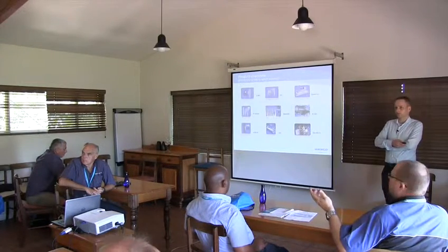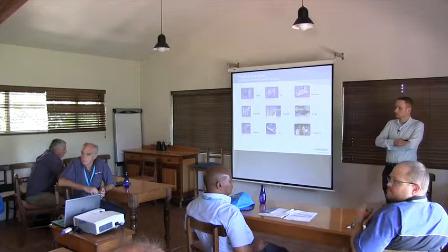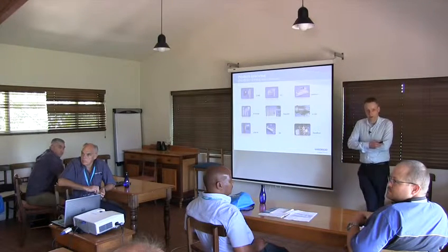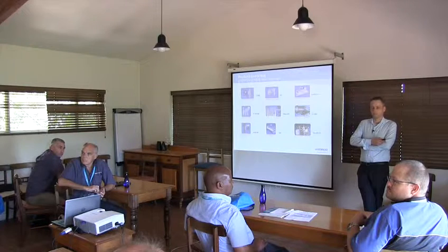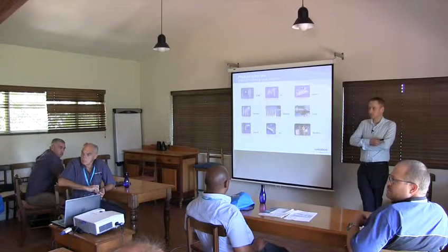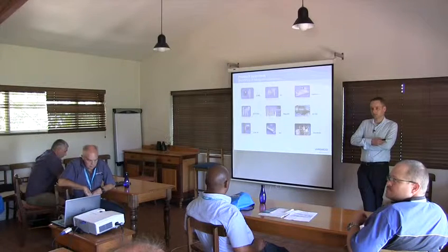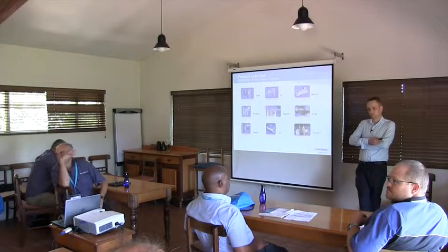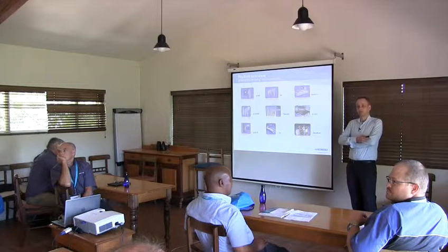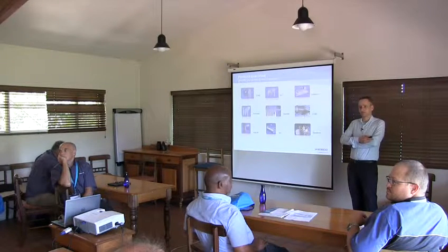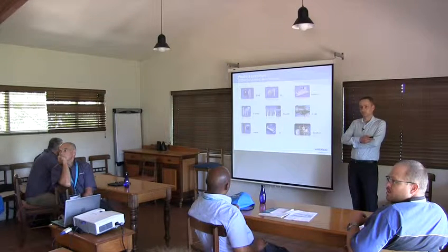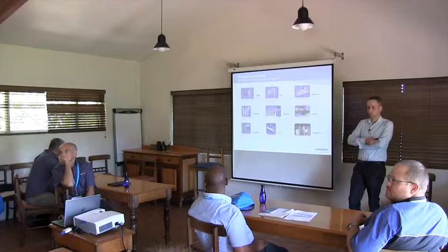If you're going to do a 2 megalitre plant, you want to base this on at least a year's water data before you commit to any process guarantees. But if you're testing water out of this reservoir and using UV for disinfection before it goes to your taps, then 1 or 2 samples will be more than enough, as long as it measures within the upper part of the measurement.